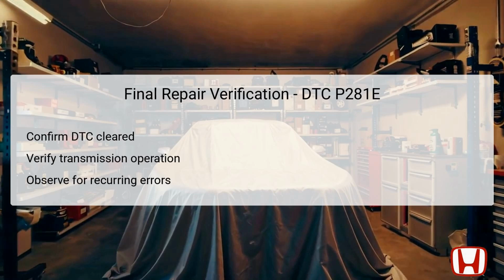After repairs have been performed based on the diagnostic process, the final verification stage is critical. Start by confirming that the DTC P281E has been cleared from the system using a scan tool. This can often be accomplished by utilizing the Clear Command feature in the diagnostic tool. Following this, it's essential to verify the overall operation of the transmission.